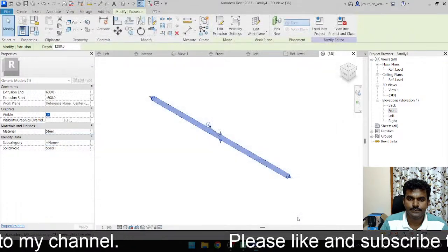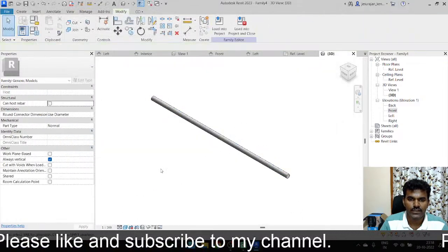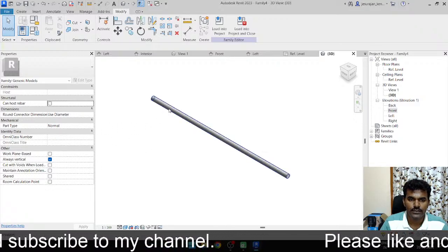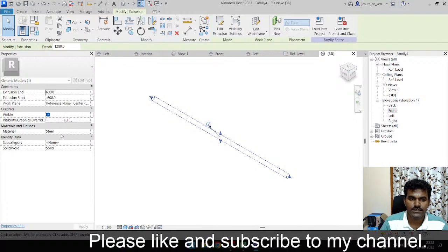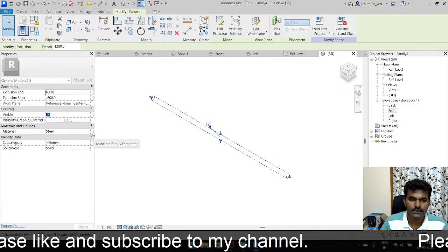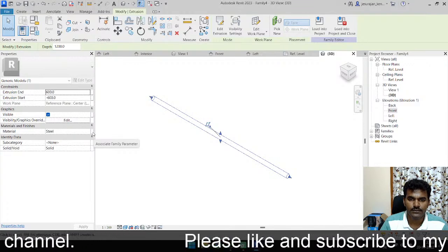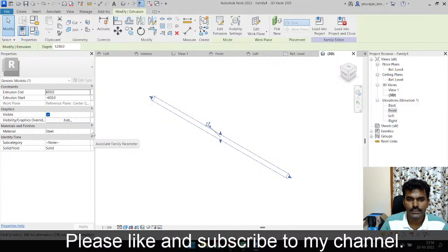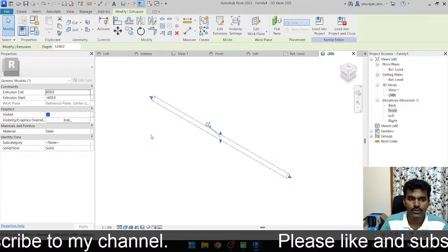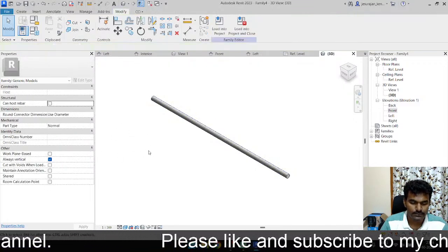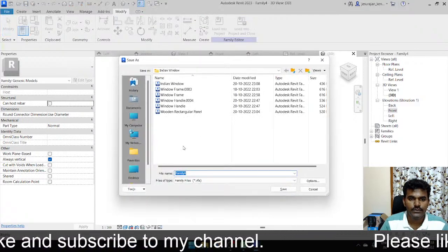Okay, it's a default material, so in case you want to make this material flexible, then select here to associate family parameter, then you can change the material anytime in the project. For now I'm not going to create a material parameter, just leave it as it is, we'll do that later.